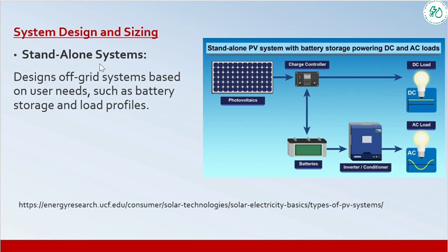Standalone PV systems are designed to operate independent of the electric utility grid and are generally designed and sized to supply certain DC or AC electrical loads. In many standalone PV systems, batteries are used for energy storage, and they are designed based on user needs such as battery storage and load profiles.